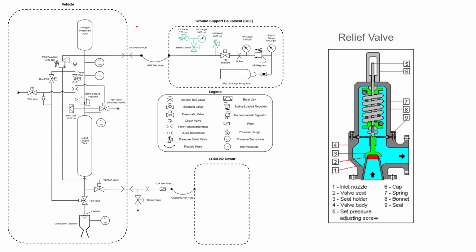When we want to launch, we would close this ball valve, which would separate these two lines and would allow us to pressurize beyond 750. And this would be once the pad is cleared and everyone's at a safe location.